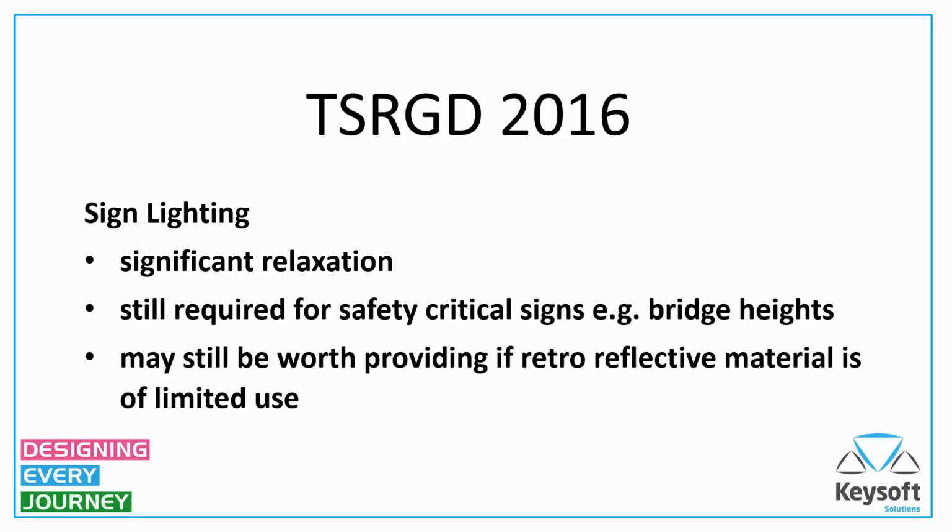Of course, by providing very good and very bright retroreflectivity to the driver, that means that the beam is more focused. So if you were coming around the corner to see a warning sign and it can't be angled in such a way that drivers are going to be seeing them easily, then sign lighting might well be worth providing.